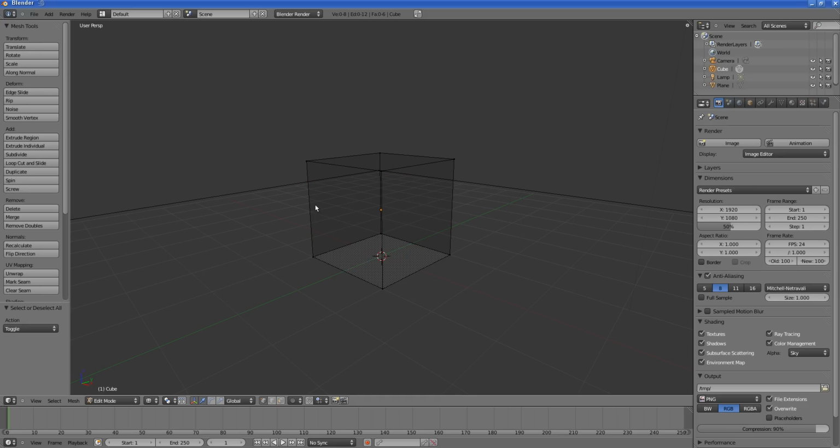And there's also lasso selection. Hold the control key and left click drag to lasso select vertices, edges or faces. You'll also notice that you can switch different selection modes from here: vertex, edge, and face.